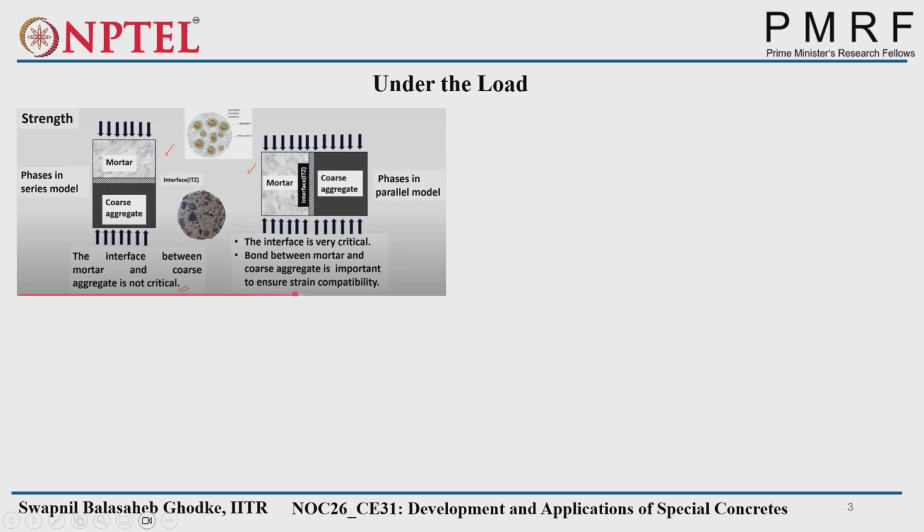In the parallel case, the stresses will differ, but the strain will be the same. Cracks will happen very initially in the interfacial transition zone itself, because that is the weakest part of the concrete specimen. We already saw in strength of materials the parallel and series phases.